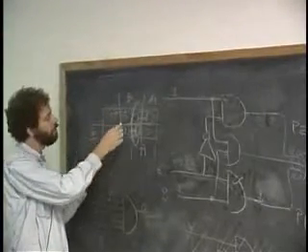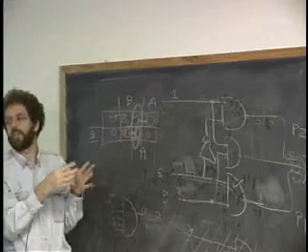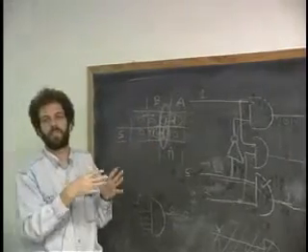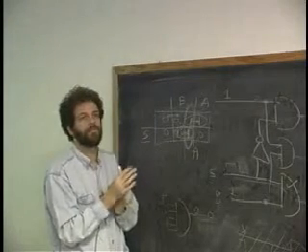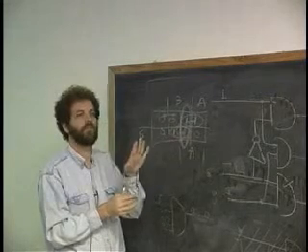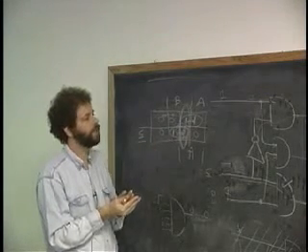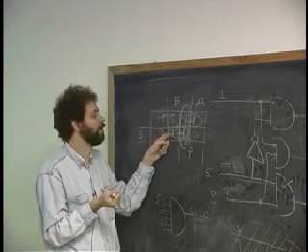Now, in terms of what happens when you go 1 to 0 and 0 to 1, we're not going to talk about that. That may, in fact, glitch all over the place. But we won't worry about that right now. What may glitch if you do 0 to 1 or 1 to 0? Let's not talk about it right now, because what it actually involves is the question of how many AND terms turn on when you go across 1.